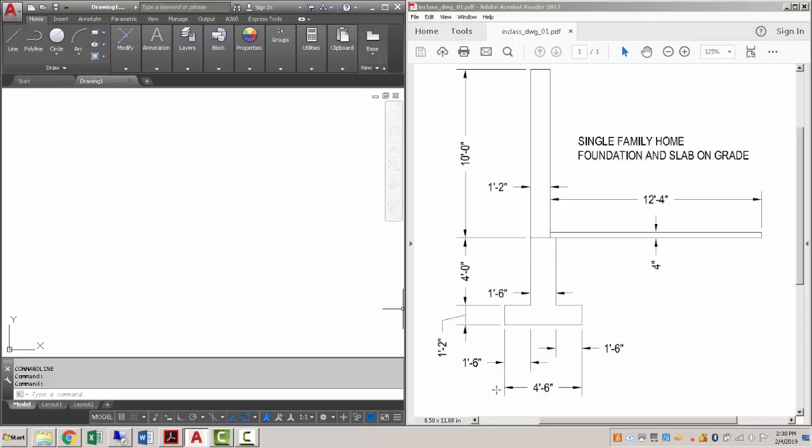So it's important to identify which parts of the dimensions are given, these extensions here and the dimension lines, and just make sure you can decipher between the dimension lines themselves and the actual object. There's two primary types of dimensions. We've got continuous dimensions, in which you're giving a series of dimensions from one point to the next, and then there's this idea of a baseline dimension.